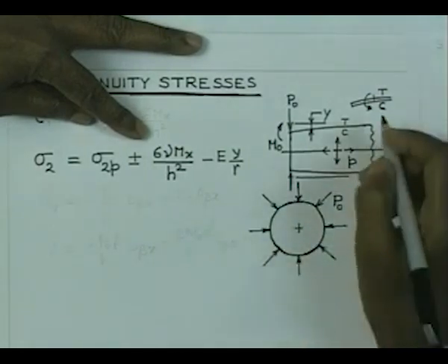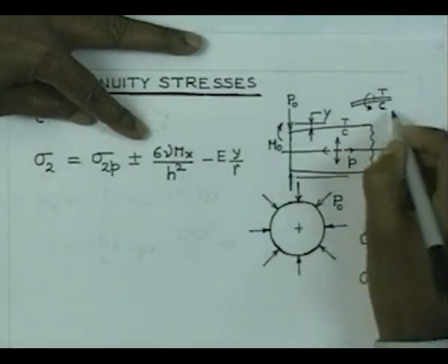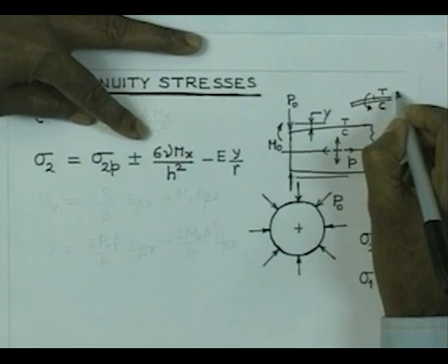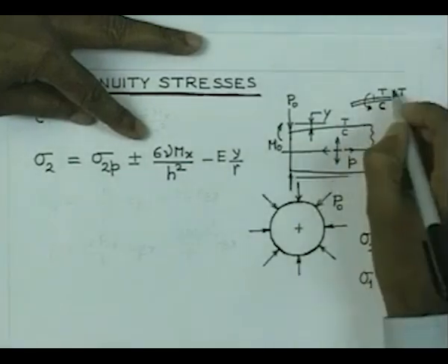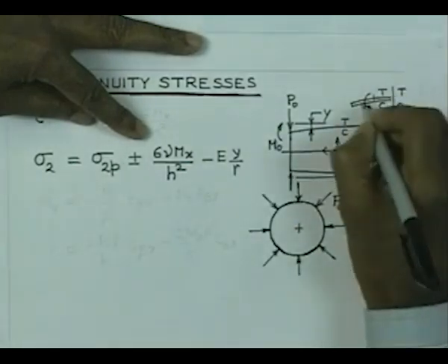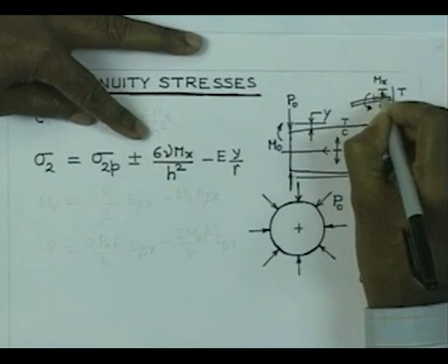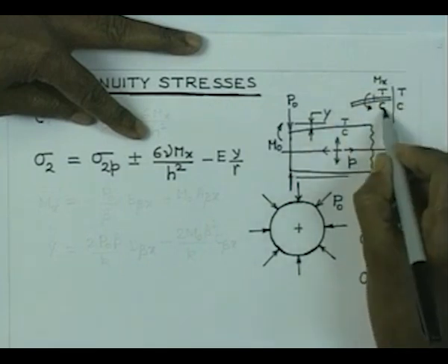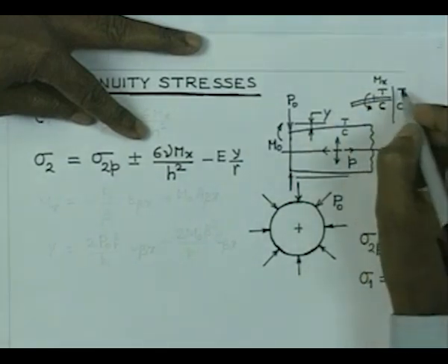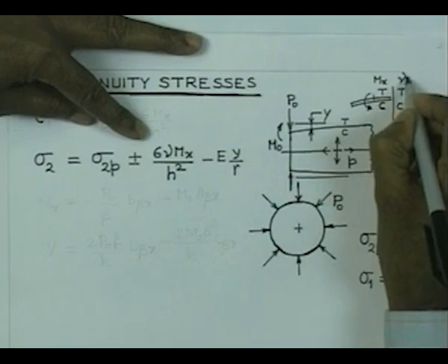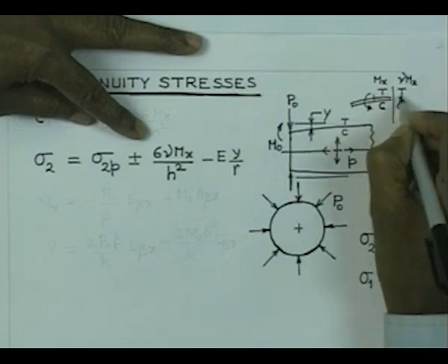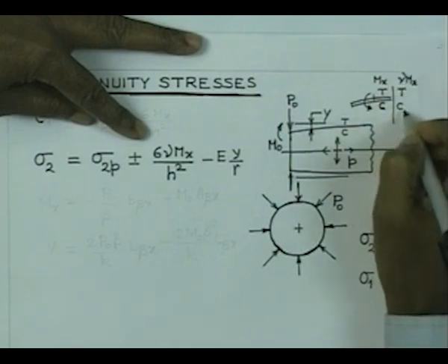So, therefore, in the circumferential direction, the stresses are going to be tensile and it is going to be compressive at this point. So, I repeat that because of the bending moment, this is due to mx, the stress going to be tensile and compressive there, and in the circumferential direction, that effect is like this, you are going to get tensile stress there, compressive stress there.